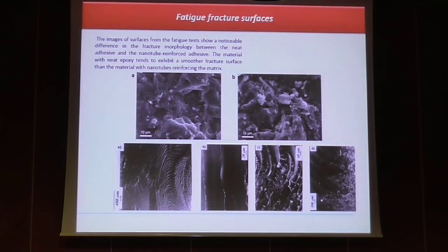And here we can see images of the surface from the fatigue tests that show noticeable differences in the fracture morphology between the neat adhesive and the nanotubes reinforced adhesive. The material with neat epoxy tends to exhibit a smoother fracture surface than the material with nanotubes reinforced matrix.